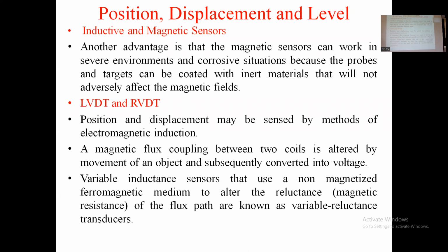When the coil starts rotating, the flux linkage to the coil starts reducing and the rate of flux cutting starts increasing. And if the rate of change of flux cutting is increasing, the induced EMF starts increasing. And at the 90 degree position, the coil side AB comes to 90 degrees.